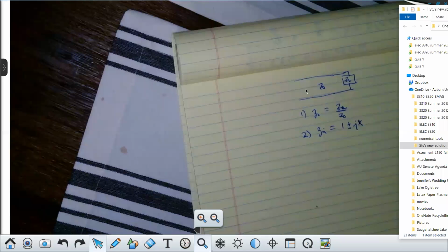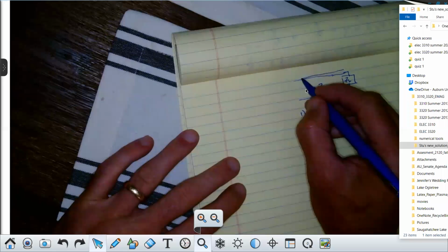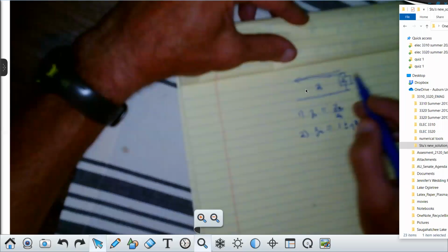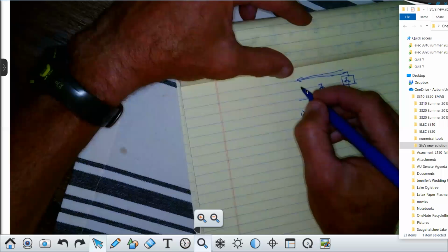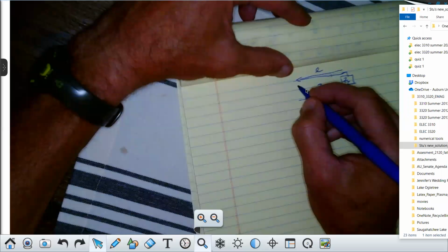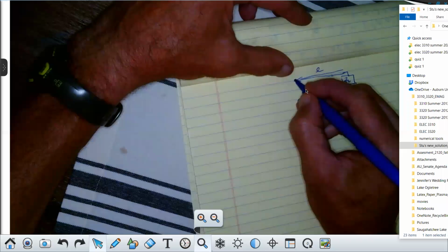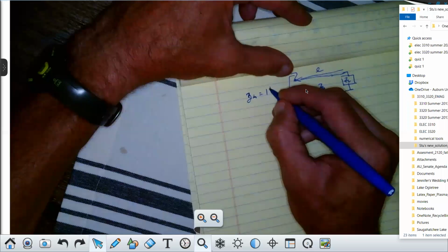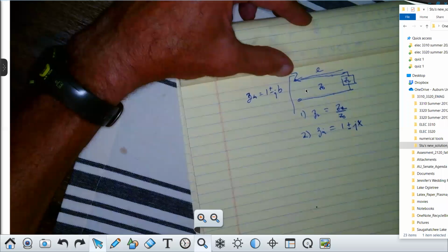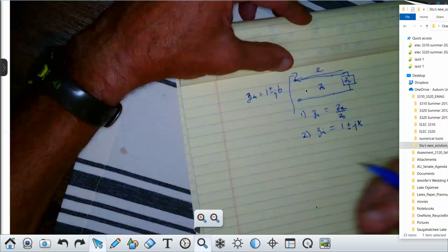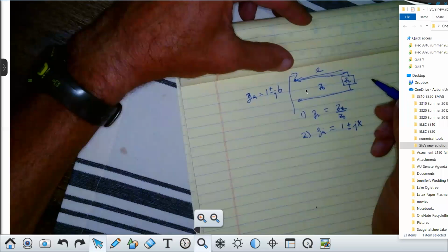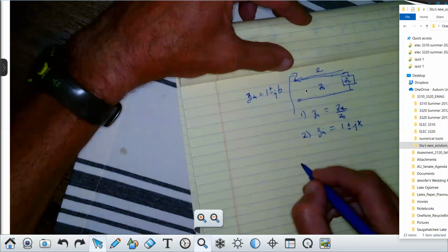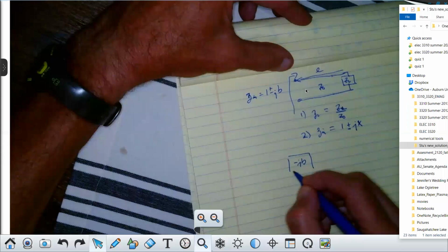And so we're moving until we get an input impedance. This is still a normalized impedance, and whatever this distance is, it ends up being a normalized Zn equal to 1 plus or minus jB. Then the next step was to get rid of the jB. We always add an element so that we cancel it. If it's plus jB, you add minus jB, an element in series. This is still impedance.